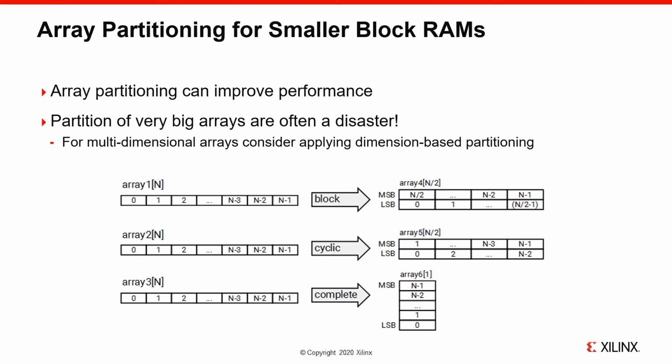The pragma HLS array partition can be used to instruct the compiler to split the elements of an array and map it to smaller arrays or multiple memory blocks, or even to individual registers in the FPGA if you do need to access all elements simultaneously. Note that the default behavior of allocating memories will be the most efficient in terms of FPGA resources.